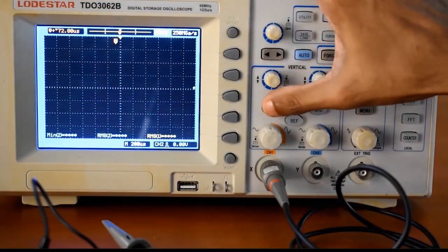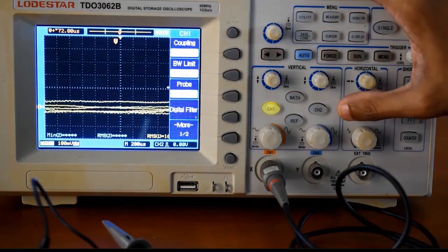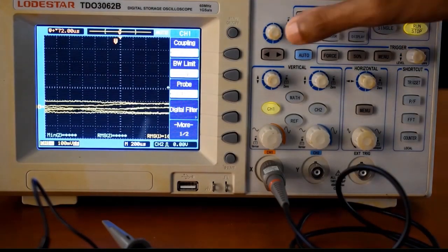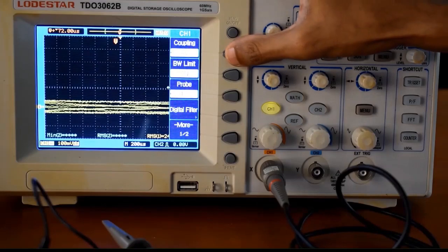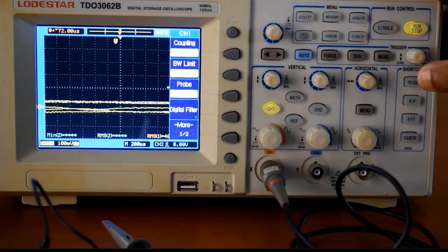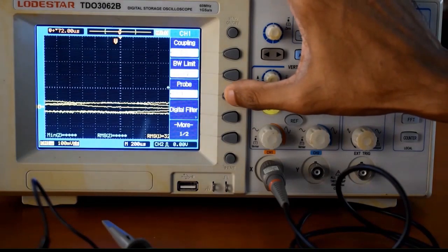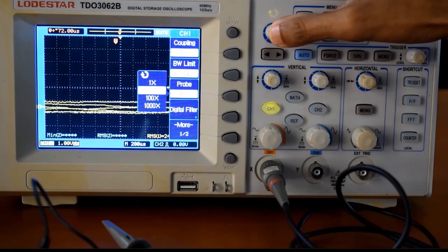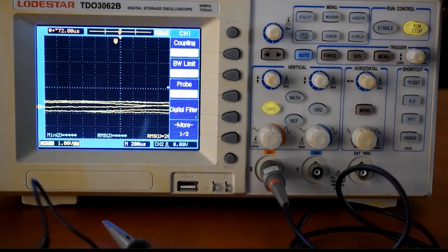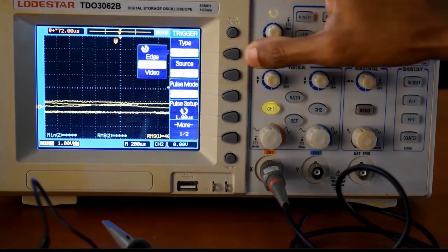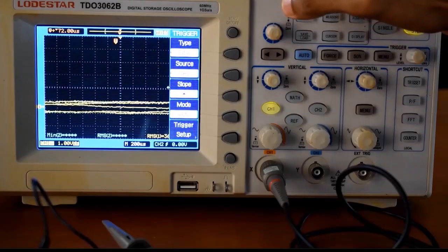We need to make some initial changes to the settings. First turn on channel 1 to see the input settings and make sure channel 2 is off. Ensure you are on DC coupling as we want to see all parts of our signal. Press the button next to probe. Highlight 10X using the top left knob and press the knob to select it. Press the trigger menu button. Make sure type is set to edge and source is channel 1.